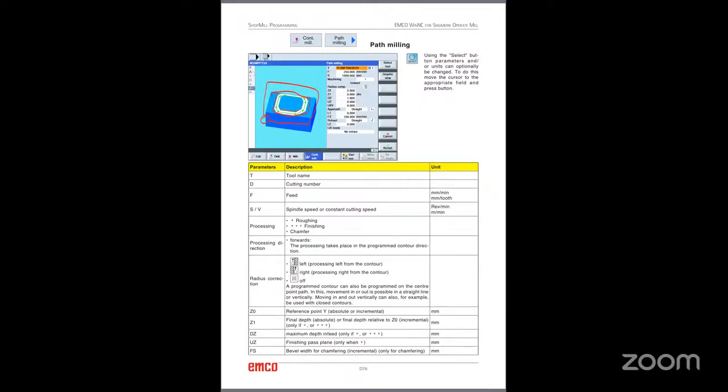After doing the roughing operation, some material will be left over. So some extra material will be there. During the finishing operation, it will remove that material so that you will get the proper dimension, proper surface finish, and good accuracy. Chamfering means during the operation, the workpiece edge becomes a chamfer. It will not be 90-degree, it will be like a 45-degree bevel.